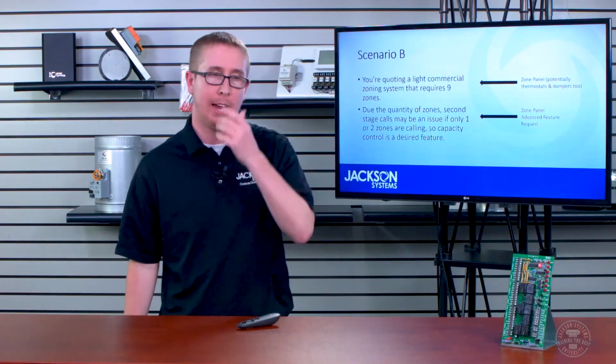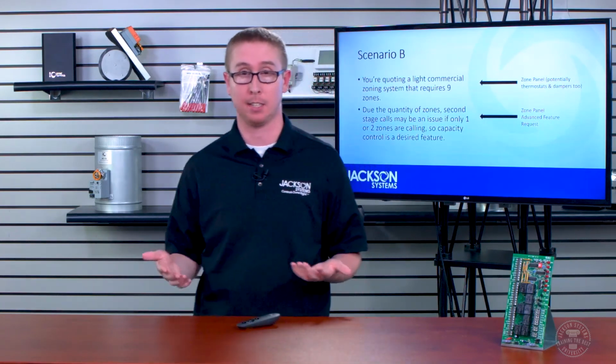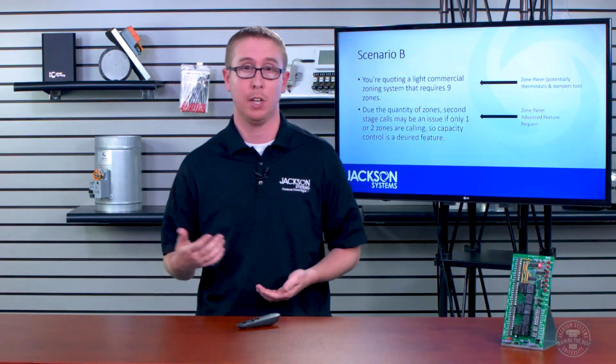Someone asked, how is an isolation relay wired up? An isolation relay is only needed if you have a large amount of 2-wire dampers, and I personally highly suggest you just install 3-wire dampers. But when it's installed, you take the damper output on the zone panel and wire it to the coil of the relay, so the relay gets energized when that damper output sends out voltage.